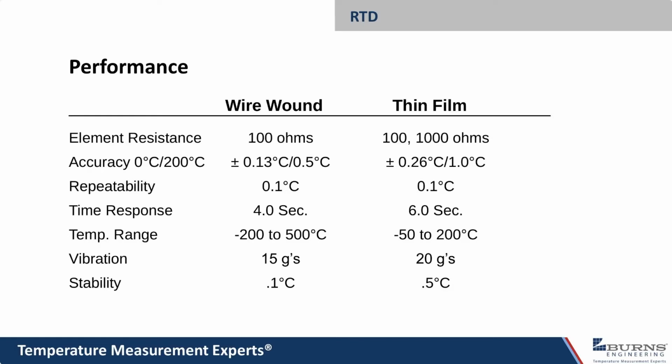It's the time constant, which is the amount of time it takes the sensor to reach 63.2% of a full change in temperature. So if you're going from 0 to 100 degrees C and you had a time constant of 2 seconds, after 2 seconds, you would be reading 63.2 degrees. So kind of a rough guesstimate of what happens there. And to get the full temperature change, or nearly so, you take that number times about 4, so it'd be about 8 seconds to reach the full temperature change.